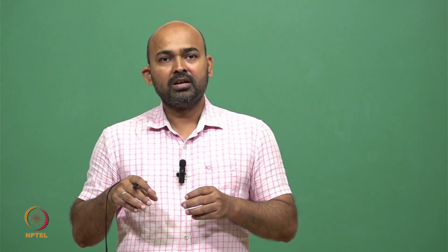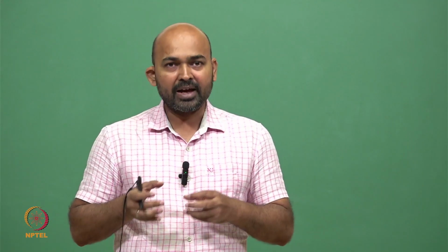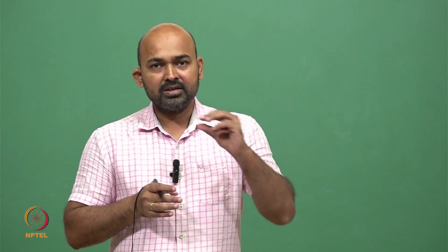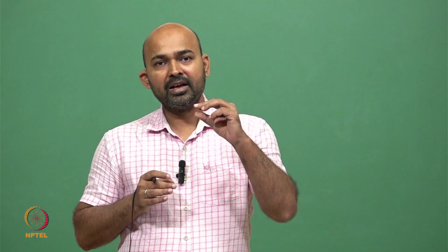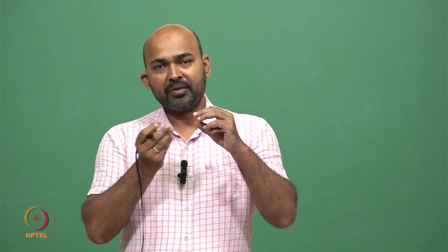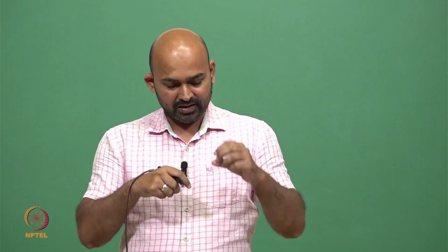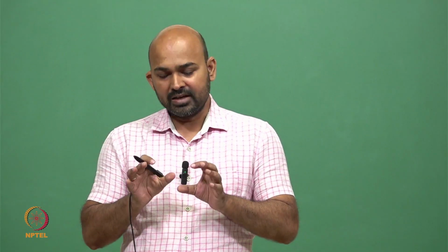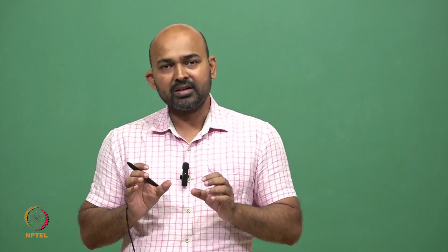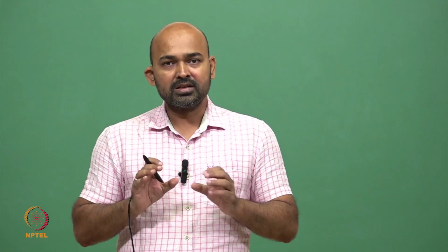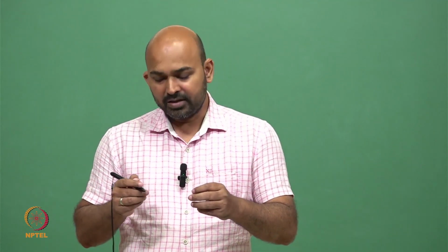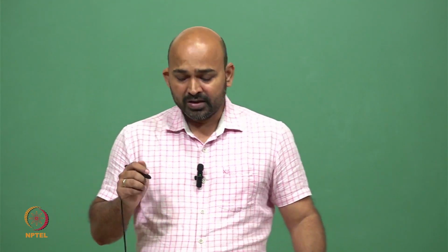However, this shielding is not as effective as in the FBAR sensor, where this material is actually hanging in the air. So there is effectively no transfer of mechanical energy through the air. But here we have a reflector stack which can prevent this loss of energy a little bit, but still there is some amount of energy which will be transferred from the piezo material to the substrate.